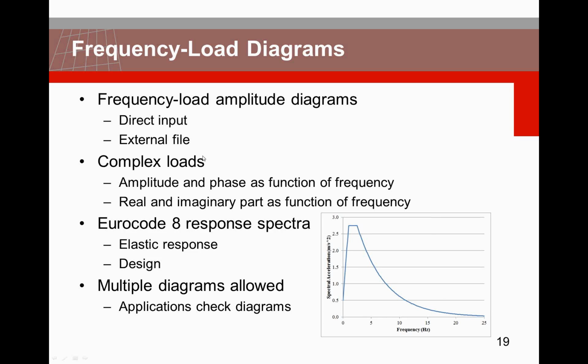It's possible with these frequency load diagrams also to introduce complex loads, because you can give either the amplitude and the phase as a function of the frequency, or you give the real and the imaginary part as a function of frequency, which can be of interest if you have, for instance, multiple loads in machinery and you have a phase difference between the forces.